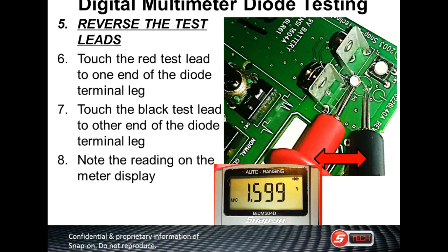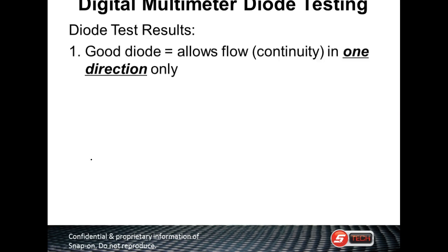Good diodes allow current to flow in one direction, but it still drops a voltage. And this is why these big diodes have to be heat sinked. Even though they drop 7 tenths of a volt, when you put 500 amps through that at 7 tenths of a volt, that's still a lot of wattage. So these will get hot, even though they're dropping very little voltage. They're not like a switch, they're solid state, so they will always drop a little bit of voltage even when forward biased.